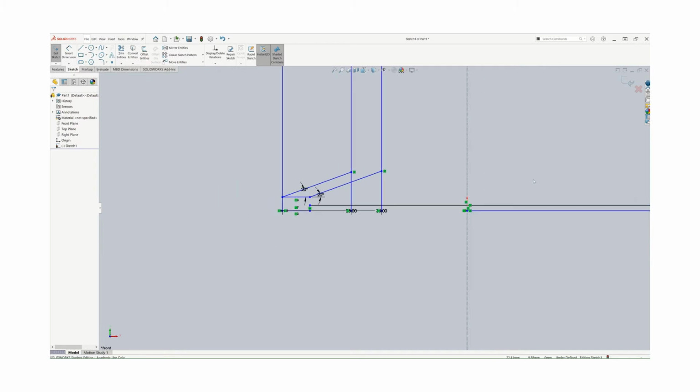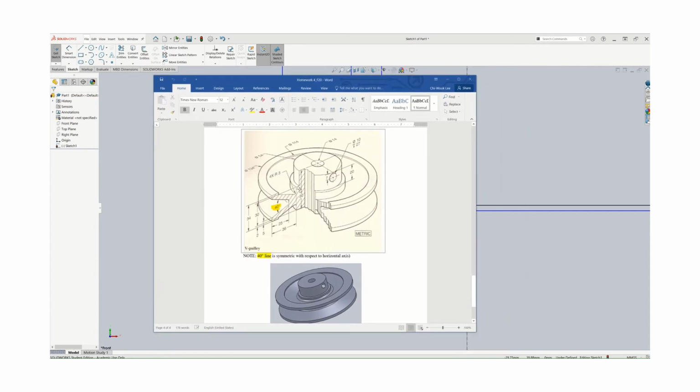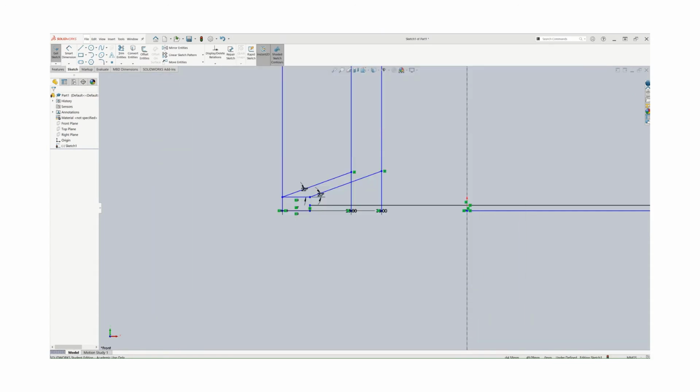And then if you want to see the top portion again, it is symmetric with respect to the horizontal axis. So one thing we could use is mirror images. To have mirror images, I could choose one of those horizontal lines and offset it, maybe by 15 millimeters. I will have the offset of the baseline right here, in the opposite direction, and that is going to be 15, and I will choose that line.